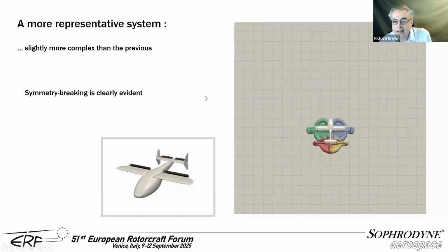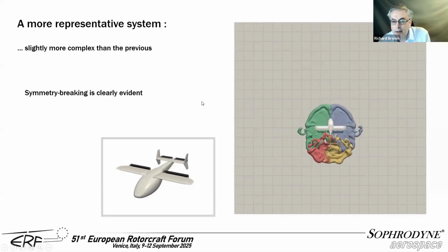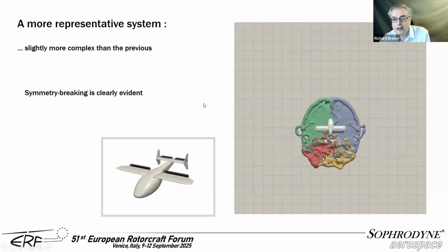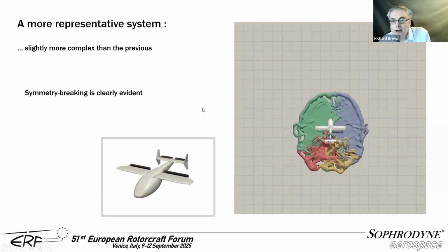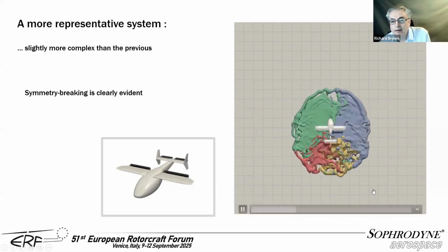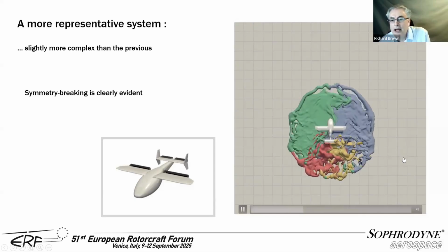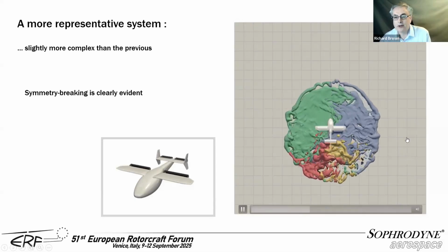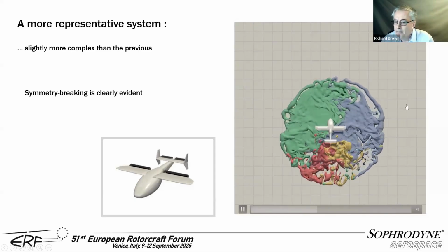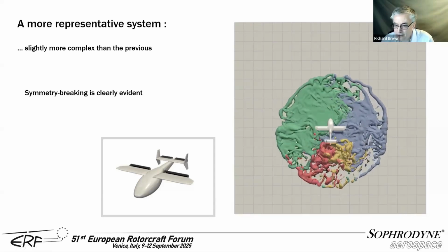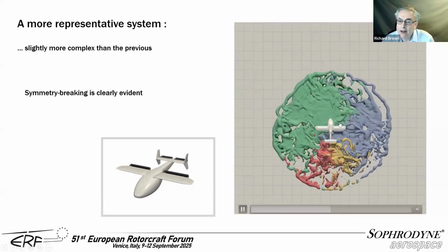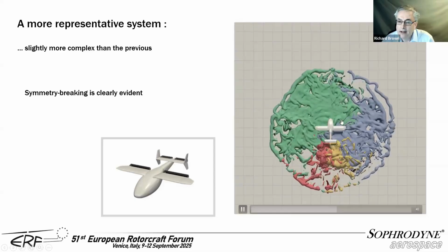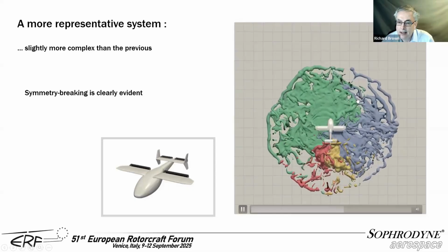So this is one of these jet lift vehicles, 4 jets, all producing a flow out towards the ground, which spreads out across the ground as an outwash. And you can see how the flow starts off in a fairly structured fashion, if I rewound, but as time progresses, that structure is lost and the flow ends up taking on a much more chaotic form. And in fact, this jet that you can see coming out the front of the head tends to meander. In this particular instance, it's pointing out in that direction.